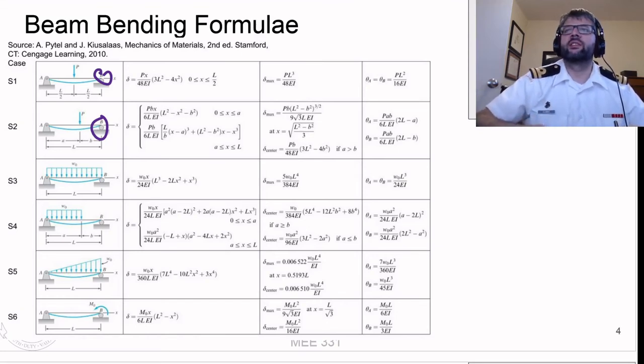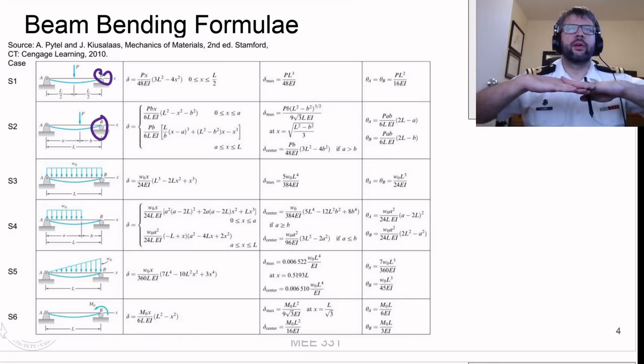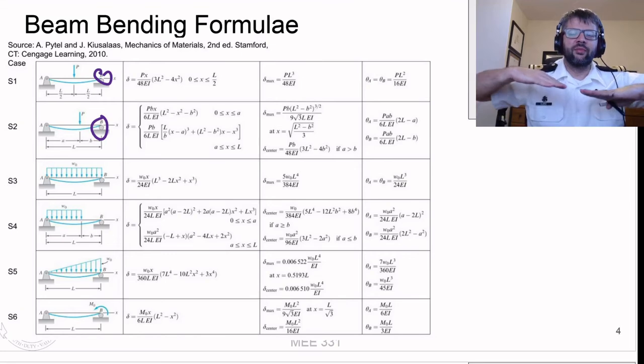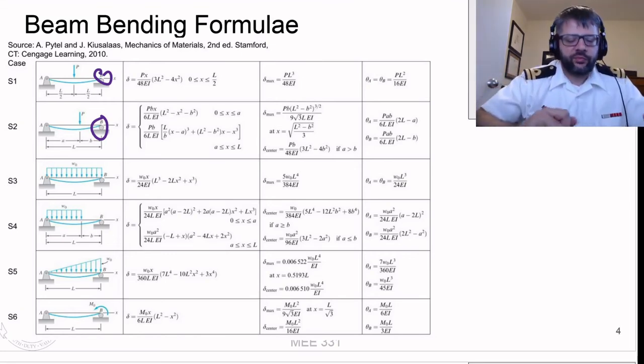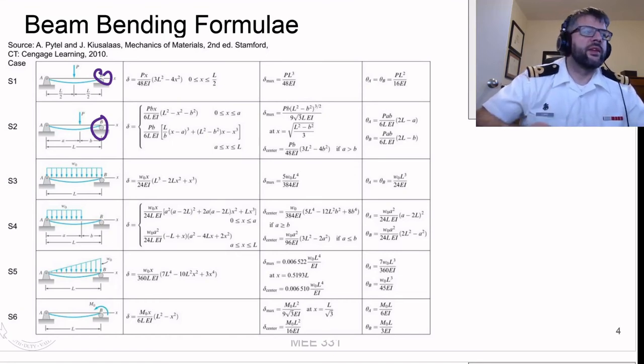And that's just to simplify the math a little bit so that we don't need to worry about how much the beam is stretching axially as we do this. If you do actually have it pinned on both ends, there will be some stretching, but typically speaking, it's relatively negligible. It's really the vertical displacements that come up a lot.